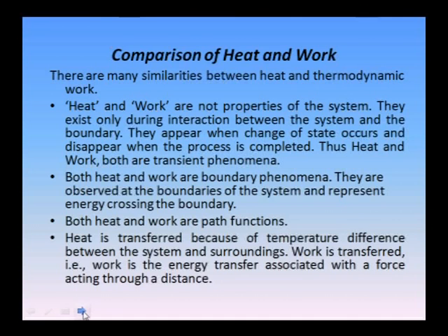When the process starts, there will be interaction of heat and work. When the process is completed, both get nullified. Thus, heat and work both are transient phenomena. Both heat and work are boundary phenomena. They are observed at the boundaries of the system and represent energy crossing the boundary. Here heat and work can be observed while crossing the boundary.